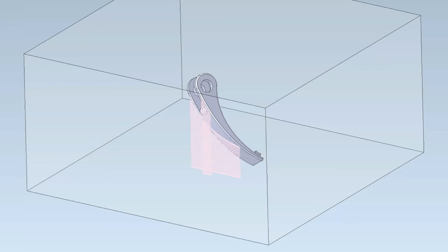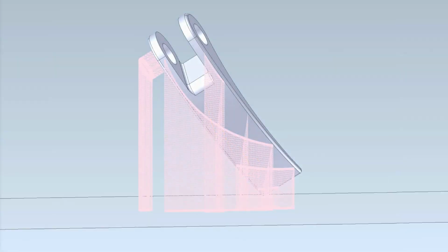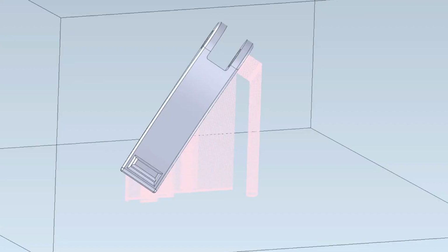Second, several attachment locations on the bicycle lever are defined with the help of CGM Modeler. Third, CGM Modeler creates a series of straight supports between the lever and a tray beneath the part. These supports have the aforementioned perforation patterns and will hold the lever during printing while conducting heat away to prevent warping. Likewise, CGM Modeler creates angled supports to support the holes.